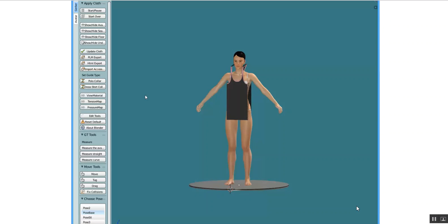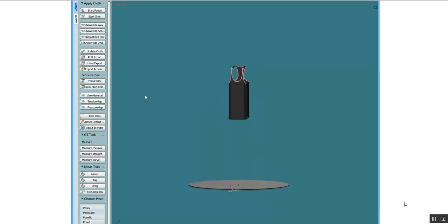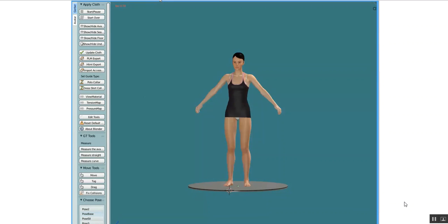Finally, the cloth simulation function will display the model in 3D. This simulation utilizes the 3D garment information defined in the model editor, images added in pattern design, and sewing relationships to create the virtual garment. Once all setup is complete, select Cloth Simulation in the Process panel of the 3D tab. The simulation will begin automatically and launch Blender.